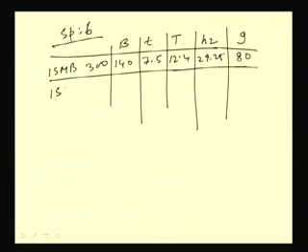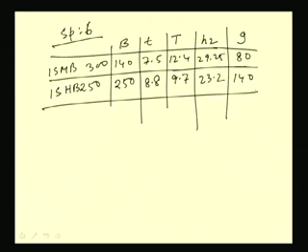And for the column ISHB 250, the width is given as 250 mm, and the web thickness for ISHB 250 has been given as 8.8, and the flange thickness has been given as 9.7, H2 is 23.2, and G is 140. So these are some parameters which will be required in case of designing the joint using seat angle.